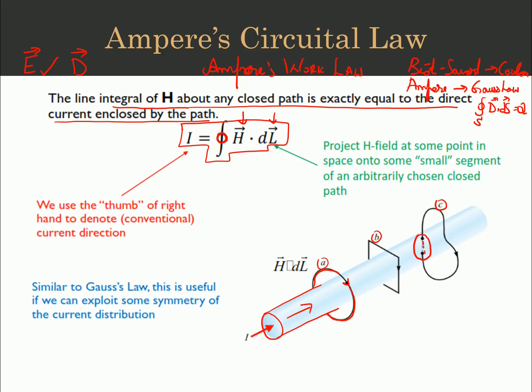Hence we can say that paths A and B exactly follow Ampere's law such that the magnetic field is completely following a closed path, but not the third, option C. It is just following half of the equation because the magnetic field is not completely enclosed, rather it is closed in some of the portion and the rest is inside the conductor. So this is what Ampere's law is telling us. So we can say that for part C there is only half of the current that is making half of the magnetic field to be generated.